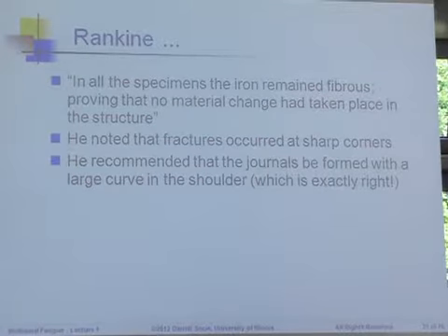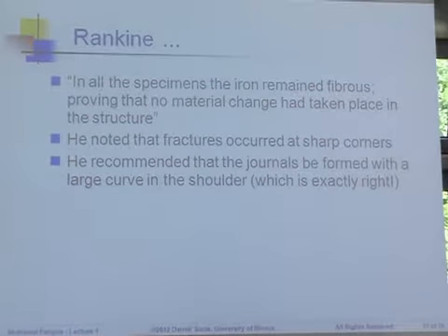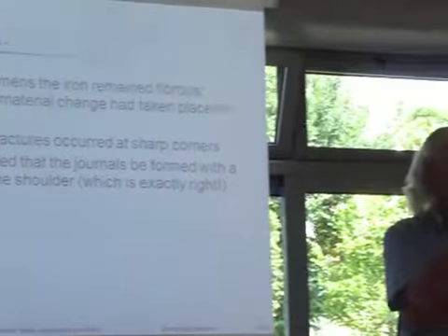So, you know, the fatigue problem and its solution was laid out 150 years ago. Pay attention to the shock loads and pay attention to the local radiuses. Same advice you would give today. Pay attention to the local radius. Pay attention to the shock loads.